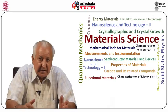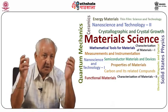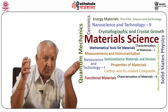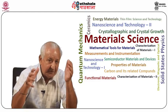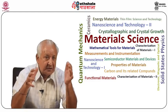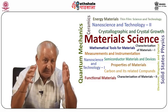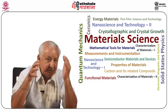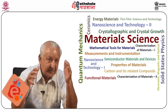So students, let us summarize what we have learned in this module. Crystal growth from pure molten phase is discussed. The concept of normal freezing, crystal pulling, zone melting, and flame fusion growth techniques are explained. Basic method of Czochralski pulling for the growth of crystals is described.